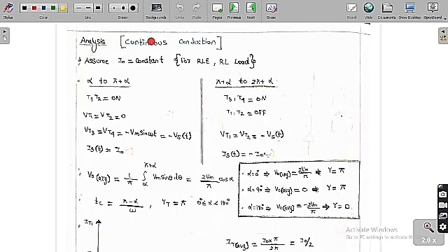So now we are going to do the analysis with the assumption that it is a continuous conduction mode, meaning the current is not at all zero, it is always a constant, non-zero value. So assume that I naught is equal to constant for RLE and RL load. We have assumed that the load is either RLE or RL load, because we are assuming that L is a very huge load. So the current will always be constant, which is what we assume here.